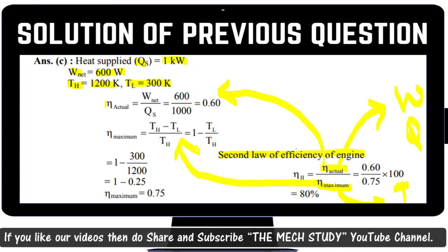This is the standard formula, 1 minus TL by TH. TL is the lower temperature, that is 300 as the ambient temperature, and TH is the highest temperature, that is 1200, where the heat is supplied. If you solve these terms, you will get maximum efficiency as 0.75, and if you put these two terms over here, then the second law efficiency of the engine will be 0.6 divided by 0.75, so you will get 80% as the second law efficiency of the engine. I hope this question is also clear. These two questions are most frequently asked questions based on the second law of thermodynamics.